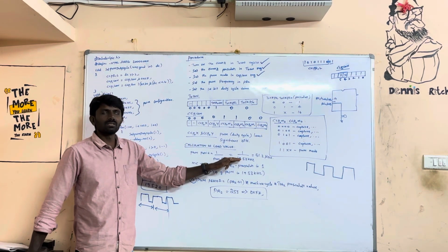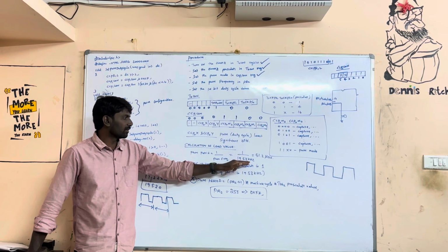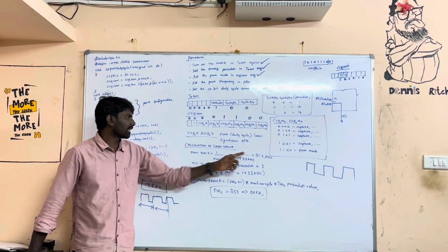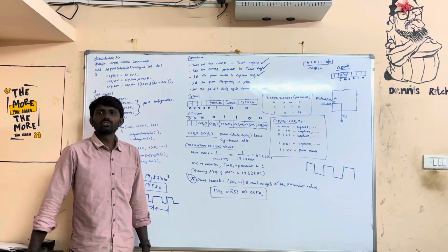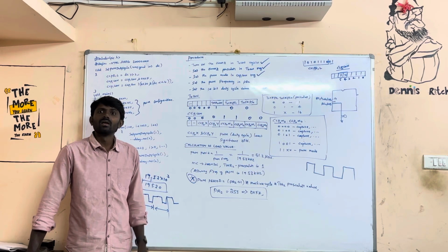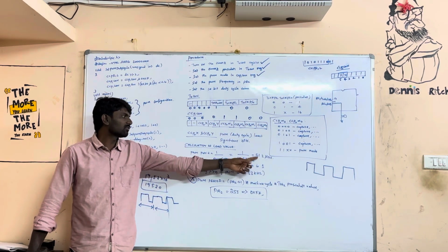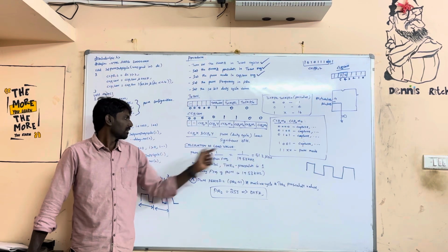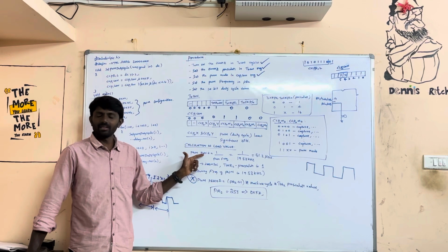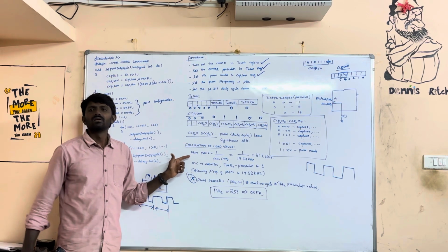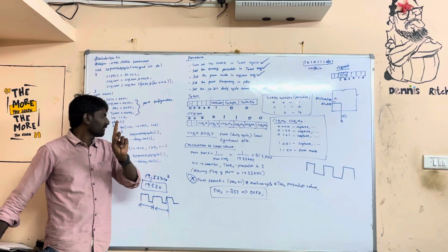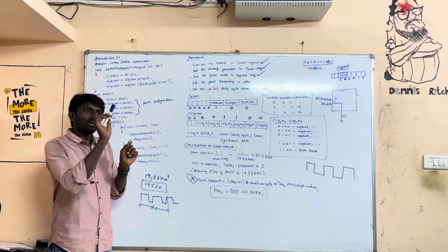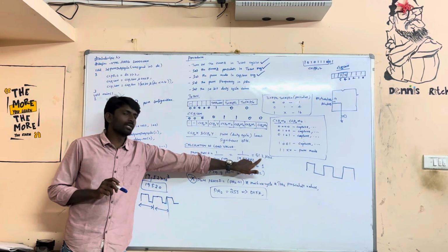The frequency of the PWM is 19.53 kilohertz. So finally, 1 divided by 19.53 kilohertz, you are getting 51.2 microseconds. What is this 51.2 microseconds? It is the period for one clock. One clock we call one clock period, right? So to generate one clock, it needs 51.2 microseconds.